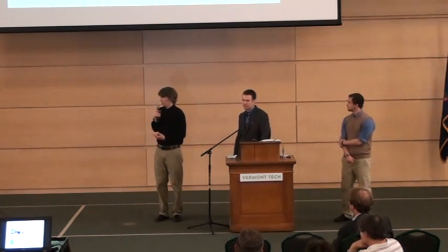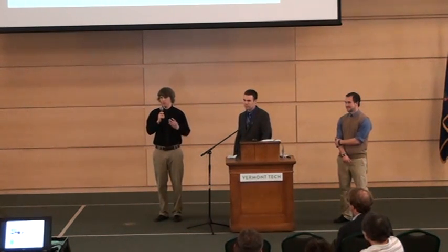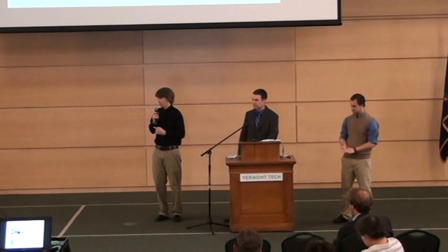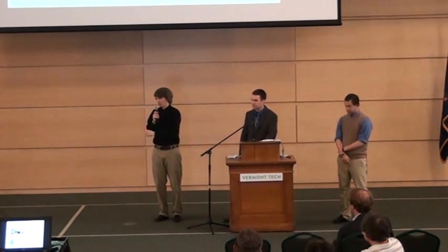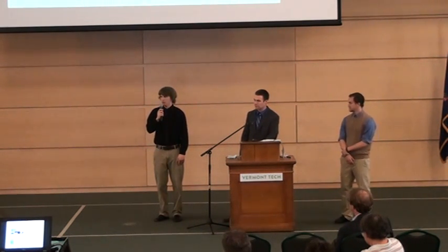Eventually, I'll run a line over to the Arduino from the DAC using one of the digital output pins, because we're using 20 of the 24 input pins for the DAC, and we use 4 of those for whatever you want. So eventually, when you start a new task, one of those will go to the Arduino and tell it to reset. Is the cycle count held in RAM or in EEPROM permanent storage? It's held in RAM on the Arduino.